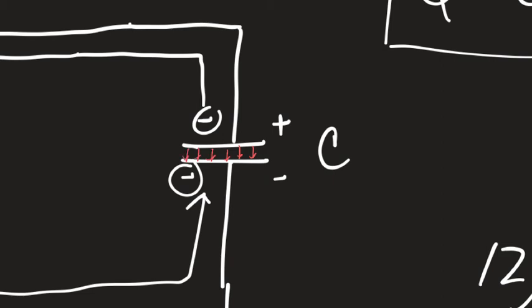And in most capacitors, it's not an air gap. There's something between the plates to keep them from touching each other. Usually it's an oxidized material, but there's something between the two plates. If you continue to increase the potential difference, you're going to continue to increase the size of this electric field. It is possible you can create an electric field so strong that electrons will begin to jump the gap from one plate to the other. They'll just jump right across. But they don't just jump right across, they tend to spark right across, igniting whatever's in their pathway from one side to the other. Mysterious blue smoke will begin to emit from your capacitor. And that's when you know you have exceeded the threshold of your capacitor.